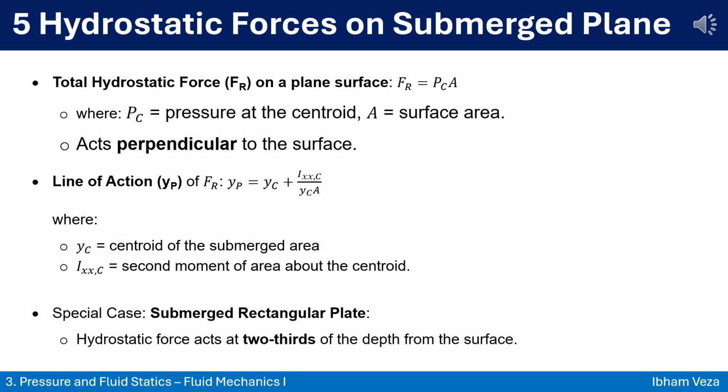But where exactly does this force push from? That's called the line of action, and it's a little below the center because deeper parts feel more pressure. For rectangles, a shortcut is the force acts at 2/3 the depth from the surface. No need to memorize complex math. Just focus on these simple ideas and you'll master it.